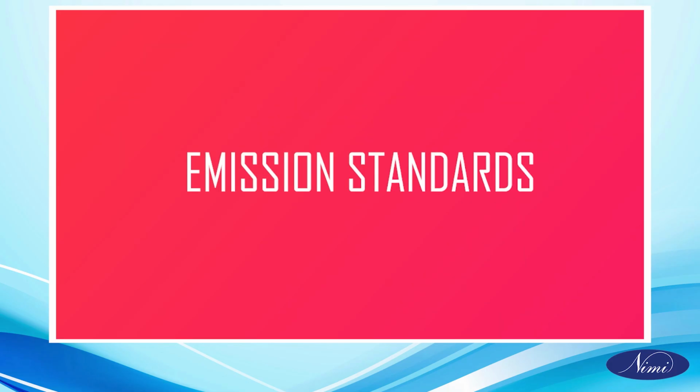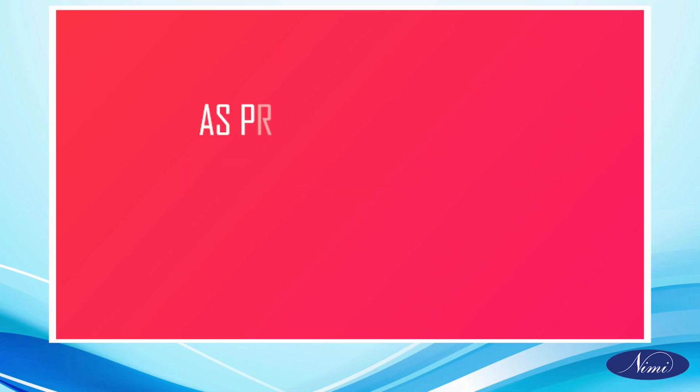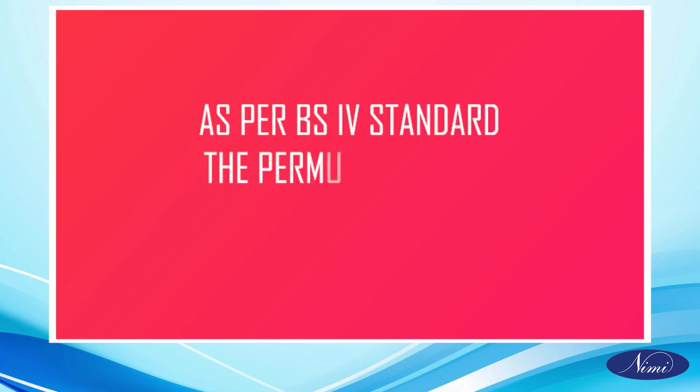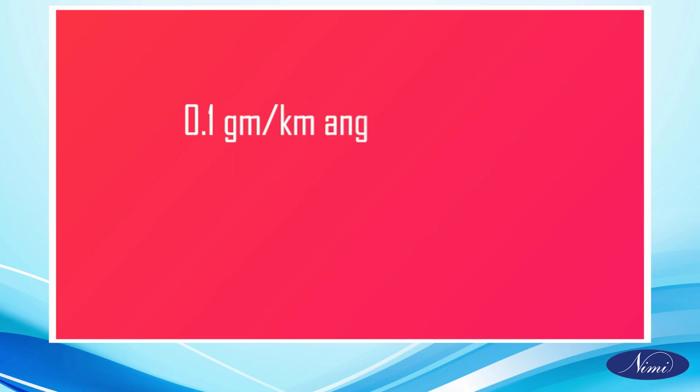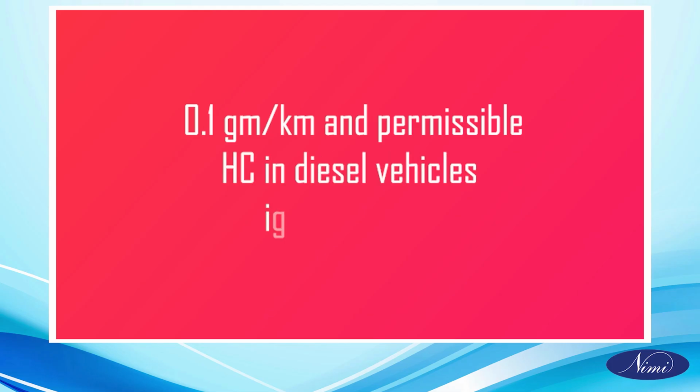Emission standards. As per BS4 standard, the permissible HC in petrol vehicles is 0.1 gram per kilometer and permissible HC in diesel vehicles is 0.3 gram per kilometer.